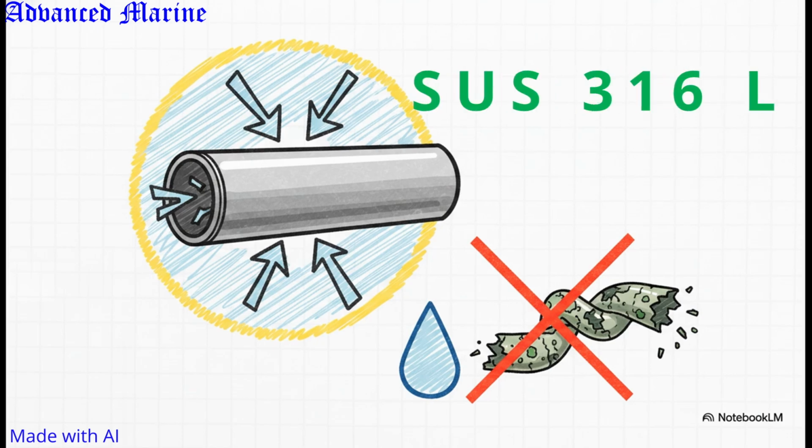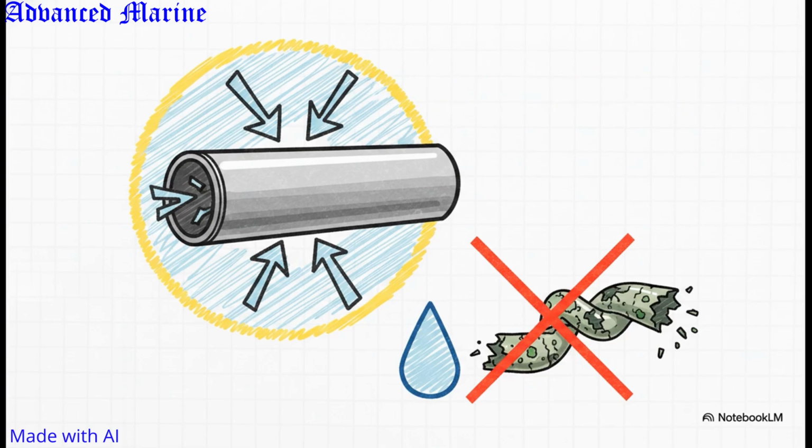Remember how copper, brass, and zinc corrode into that greenish-blue mess with just a drop of moisture? Well, SUS 316L is chosen for its rugged durability and total immunity to that specific alkaline attack. And it's forged to a high-pressure specification because an ammonia system is constantly under immense internal forces. The pipeline literally must never bulge or stress under that load.